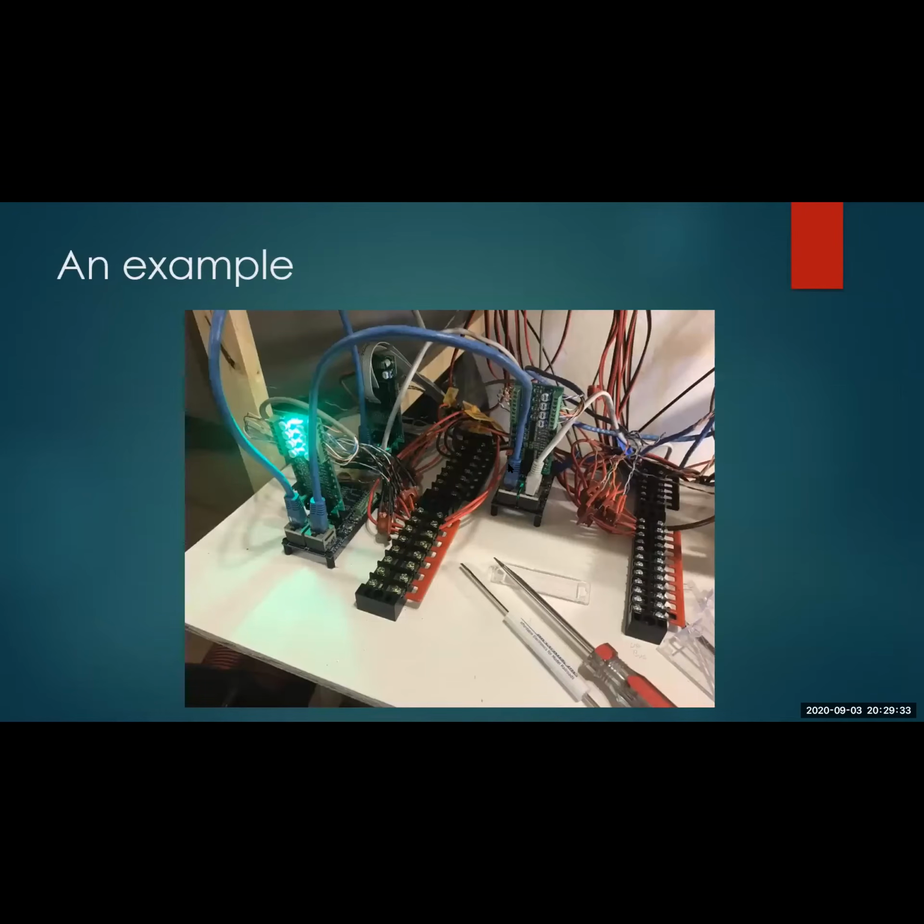Your wiring is much neater than mine. Well, until you got to this picture. Yeah, it didn't look so pretty after I got all the field wiring in. But really, that's how I put it all together. I just mounted the different nodes onto little standoffs on the board. I got these barrier strips going, and all my block wiring then came back to a common point. And here's where my DCC buses were coming in. Made it pretty easy. It's an example, guys. There's probably a lot better ways to do this, but it worked for me.